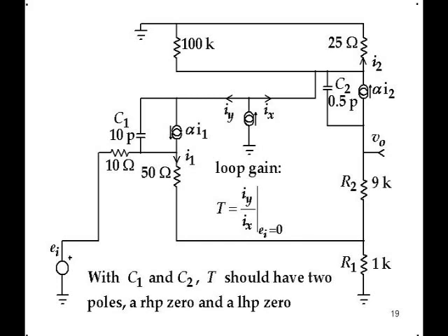And even though this injection technique has become pretty widely known now, and it can be done in practice in the hardware as well, there's a caveat on whether or not you should believe the result. And the caveat is, what is the ratio of the impedances seen looking forward and looking backwards from the injection point where you're putting in the test signal? And that impedance ratio has to be infinite to do one kind of injection. It has to be 0 to do the other kind of injection, current versus voltage. That's why you get the wrong answer. This is not an ideal injection point.